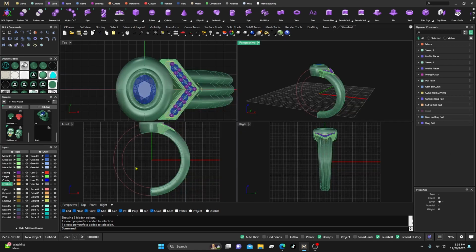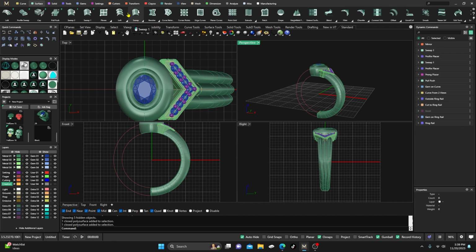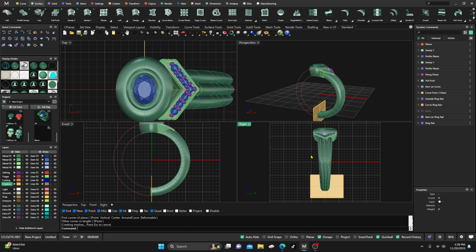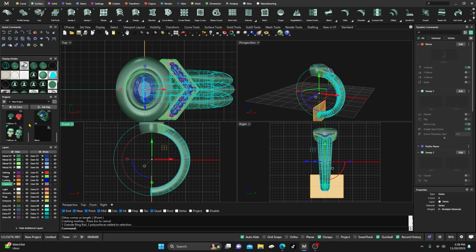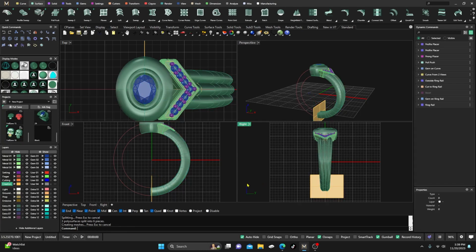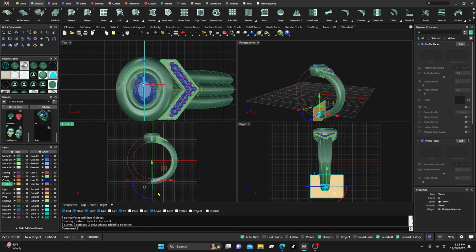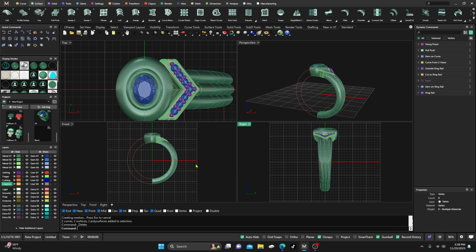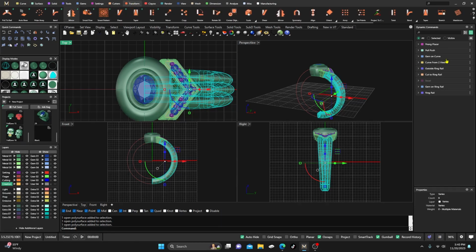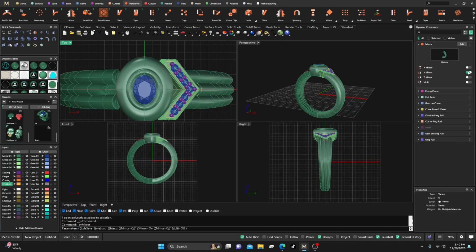Well, the best way would be to go to your surface and grab a plane, since I put all those things out there now. And then grab those three, minus our ring rail, of course, and then split with this here, and then hit enter. So it gets rid of all that, and so we can select all this down here, and we can delete it, right? And then we can take this one, and this one, and transform, mirror in our Y direction.